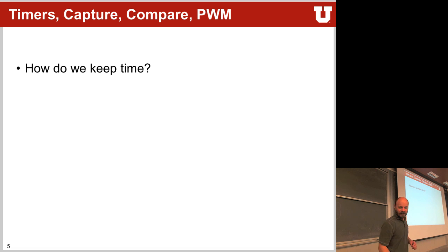I will write it down. So if F0 is 1 megahertz, 10 ppm of that is 10, no units, right? So then our frequency will be at 1.000010 megahertz.